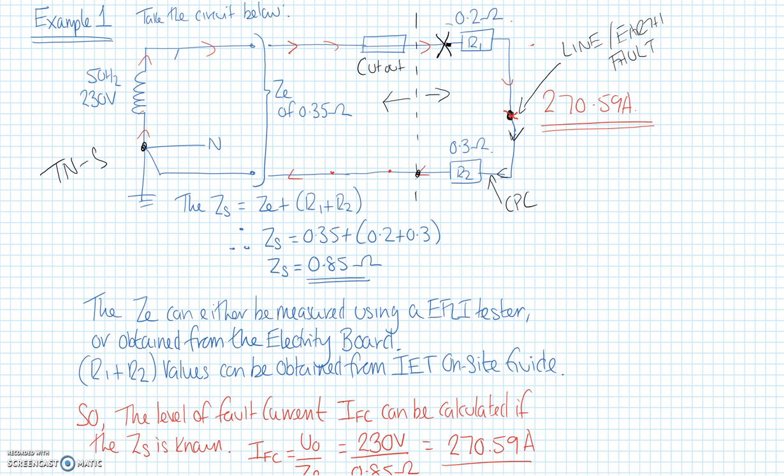I'd imagine for design engineers who are designing installations before anything's built, doing it per pure design, that information would be quite valuable to determine the exact size of cabling required in order to hit our resistance values. So 0.85 ohms, we can see there, the 0.2, 0.3 ohms on the R1, R2, we have the autonomy to select this cable size to whatever we want it to be.